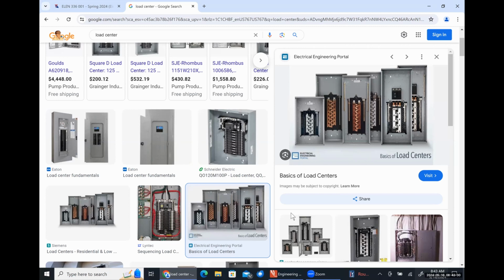But I talked a little while ago about how in an apartment complex, you might not have 240 volts because instead the apartment complex is fed through a three-phase system. So their access is going to be either between the A and B phases, where they would have 208, or the A and neutral phase, where they would have 120 off of their transformer.